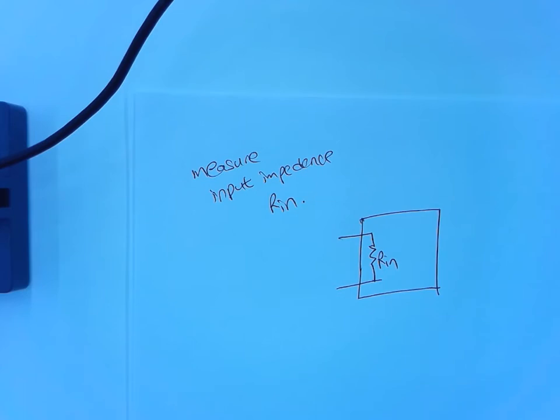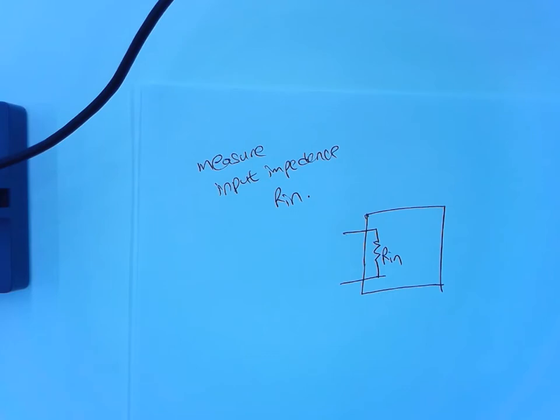I'm just going to take a digital multimeter and connect it. Is there another way? Look at the specs. Okay. Usually, the problem with digital multimeters is that when you have very high input impedances, they're not very accurate, because multimeters have their own input impedances, which are around megaohms. Amplifiers also have input impedance around megaohms, so they will not be very accurate.